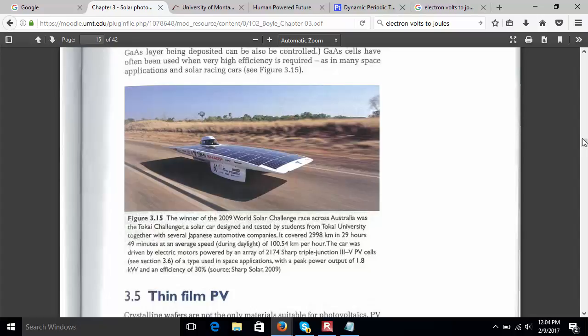We actually did this a couple of years ago in our practicum. I had my students hook up a couple of 12-volt computer fans to the cells, and at a certain temperature they kicked on. The fans themselves were pulling 2 watts, but the panel bumped up by 4 watts. The temperature is hot, which diminishes the efficiency of the cells, but if you have that convection, you're constantly cooling them and preventing the buildup of heat. Yeah, air cooled. And they said Sharp triple junction PV cell, 30% efficiency.